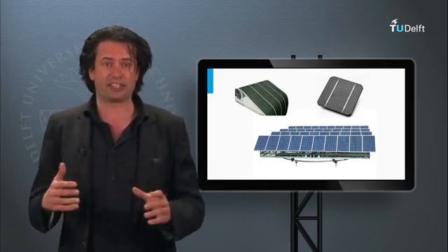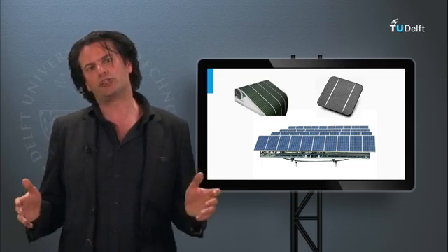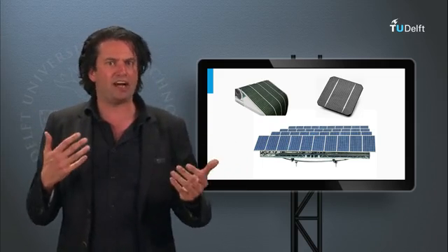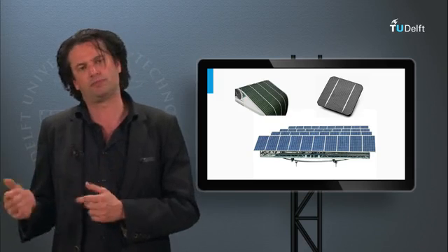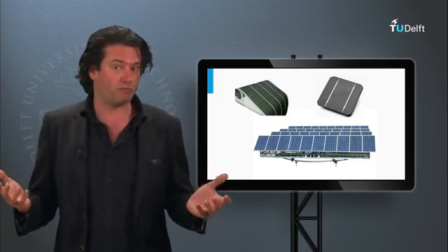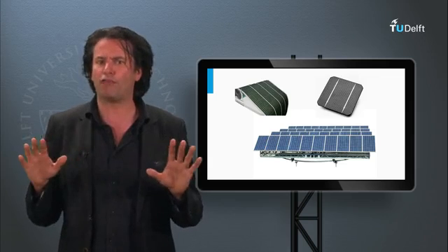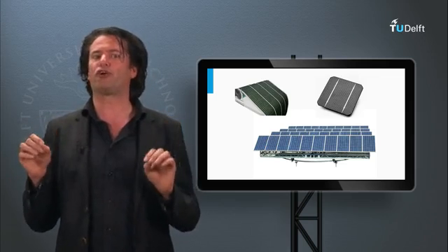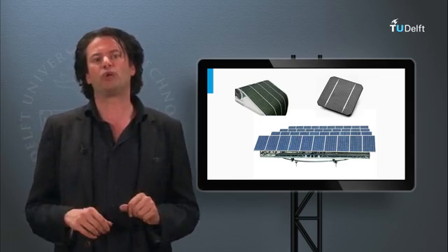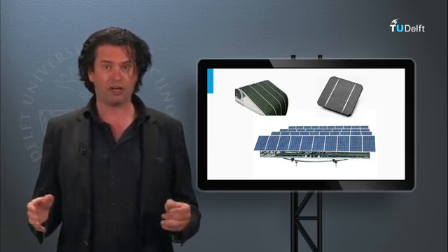But conventional crystalline silicon modules are also very bulky. Polycrystalline silicon modules cover a lot of area. Monocrystalline modules are more area efficient but are more expensive. Amorphous silicon modules are cheaper, lighter, and sometimes even flexible, but give poorer yields. So there is plenty of optimization to be done just for the choice of your ideal PV module for your system. The optimum choice will of course depend on the location, ambient conditions, the budget you have, among other factors.